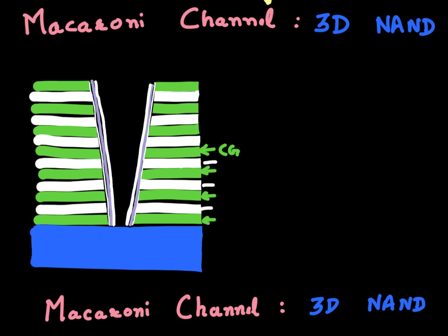processes work, that when you start the etch, you have more influx of ions or radicals which are creating this etch, and as you essentially go down the structure, that ion density decreases. So when you open a plug like this, it would always be wider on the top and more narrower on the bottom. Okay, so now I'll initially fill it up with all these dielectric layers which would form